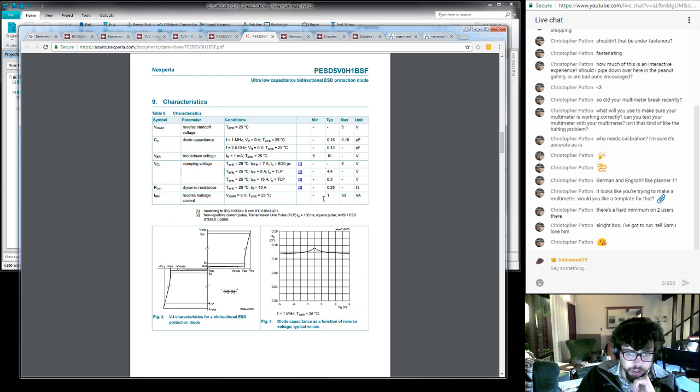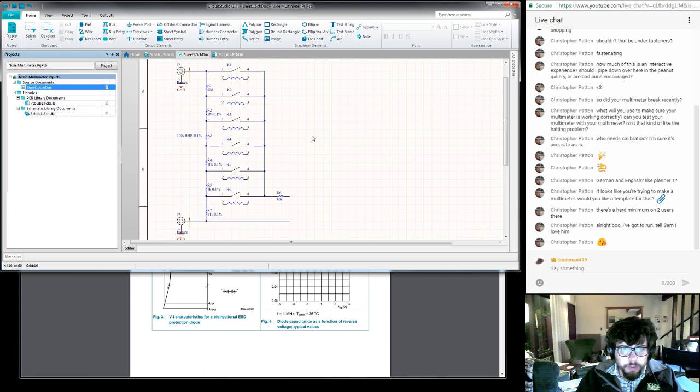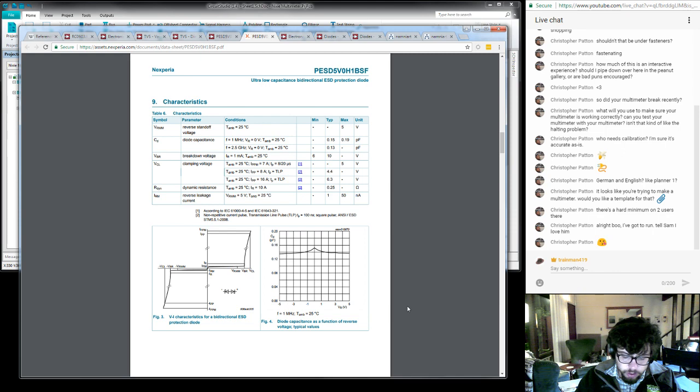This nanoamp leakage number, particularly at 50 nanoamps. Well, that doesn't sound like much. If I'm in one of these lower ranges, and I have 10 megs of input resistance, that 10 to the 6th input resistance, if I do calculations over here, times, what's my leakage?